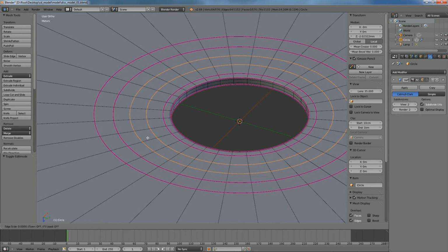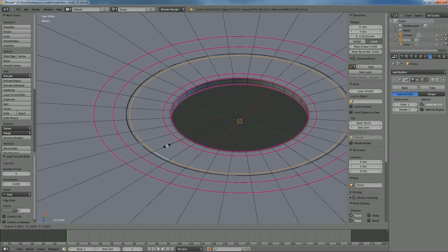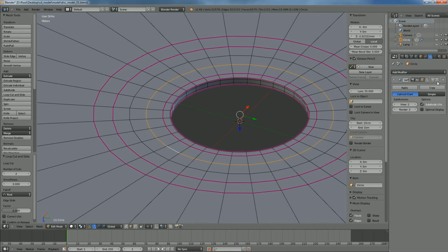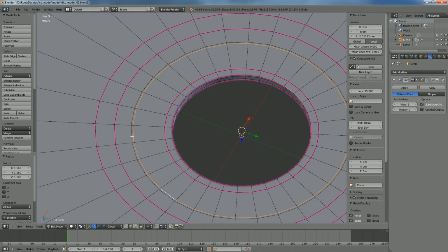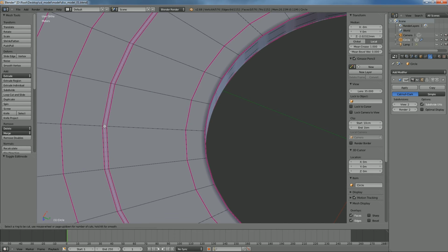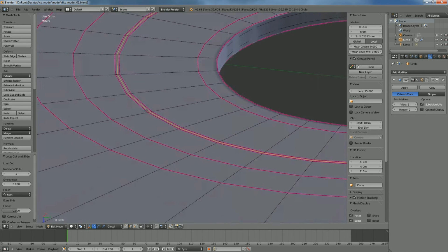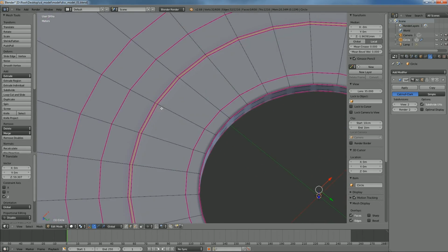So we'll just take two edge loops here. We'll just scale one close to the other. Actually, here we'll turn off the editing cage for edit mode. And if we just scale it out, and we go ahead and mean crease both of those so those don't move around on us, and then we add an edge loop between them, and we move that one down on the Z-axis, or I guess up towards the top.